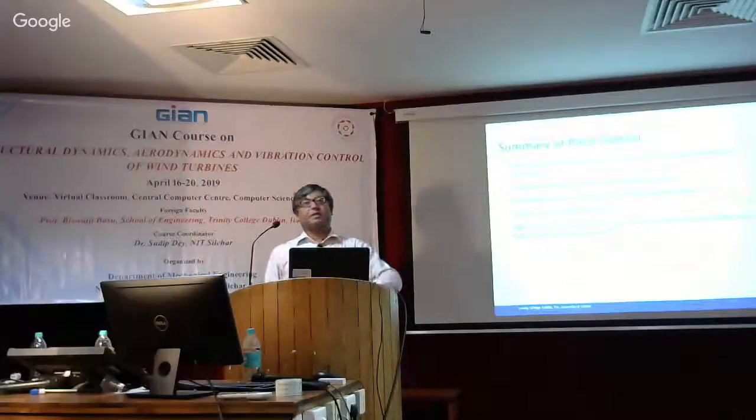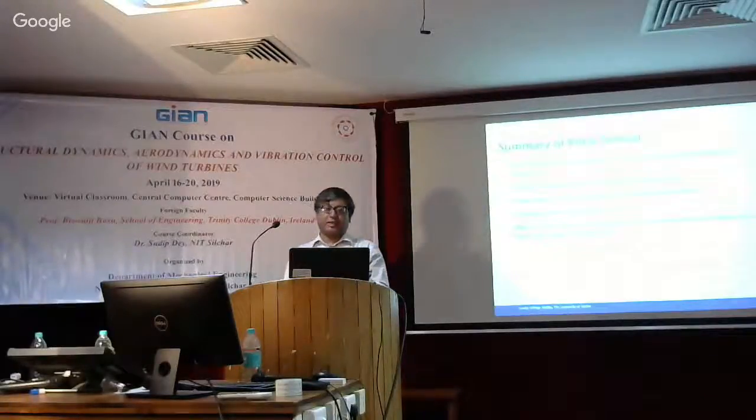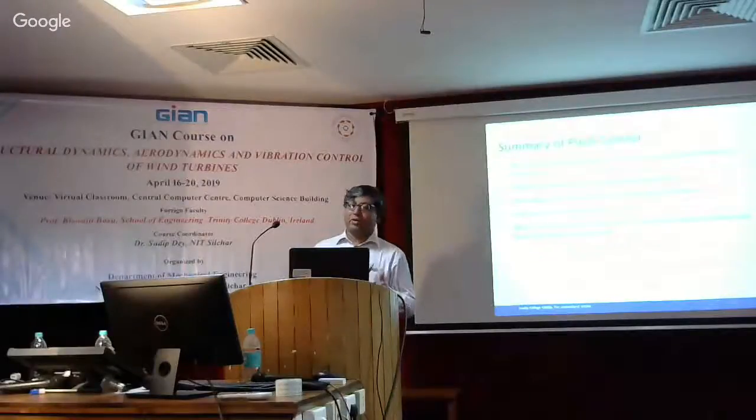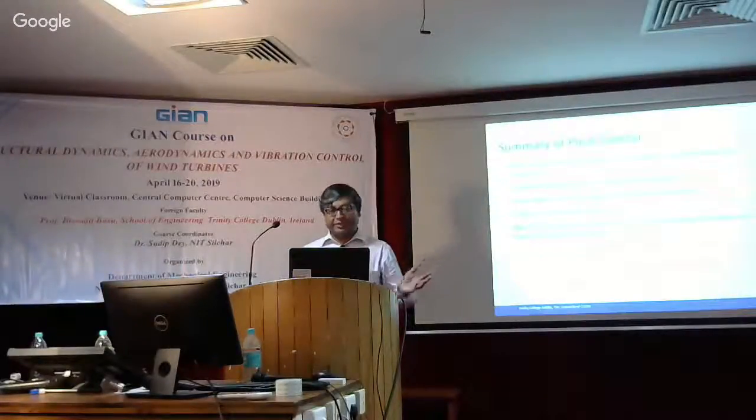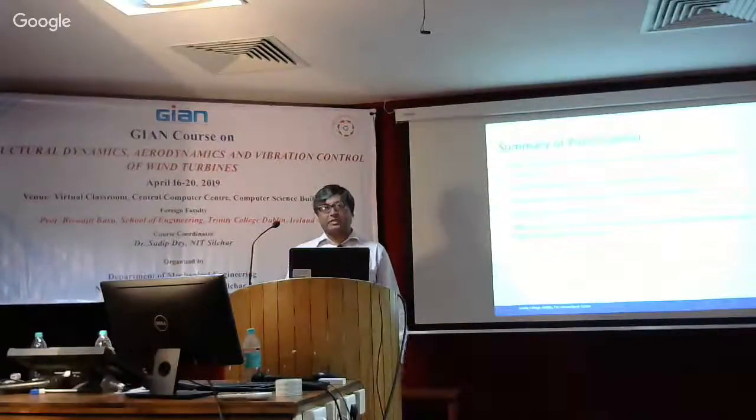But with variable speed, you also have the option of controlling the torque. So pitch control and torque control can also work together. And you can have individual and collective pitch controls with various degrees of benefit. And the effect of the pitch controller, particularly on tower and drivetrain vibration, is very clear. And finally, blade load also gets reduced.